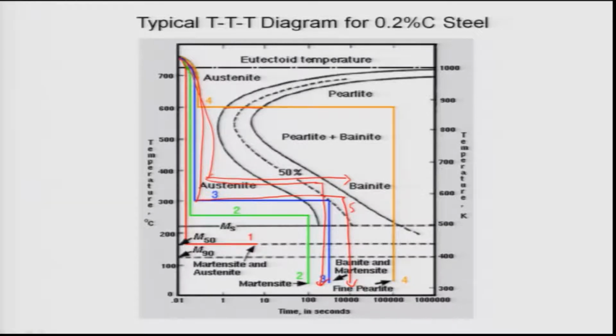And once pearlite forms, the sample can be easily cooled, because once complete transformation of austenite to pearlite happens, nothing else can happen, whether you quench it or you cool it slowly, it does not matter. But normally it is cooled rapidly so that the pearlite which is formed at high temperature does not get changed when it is investigated further.